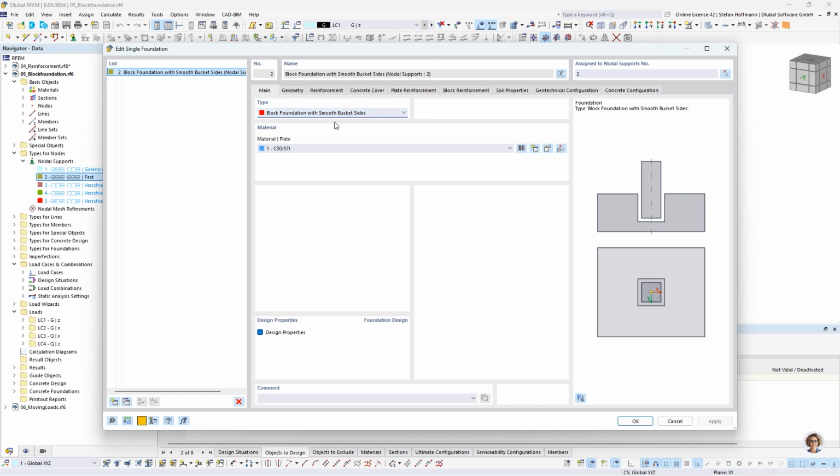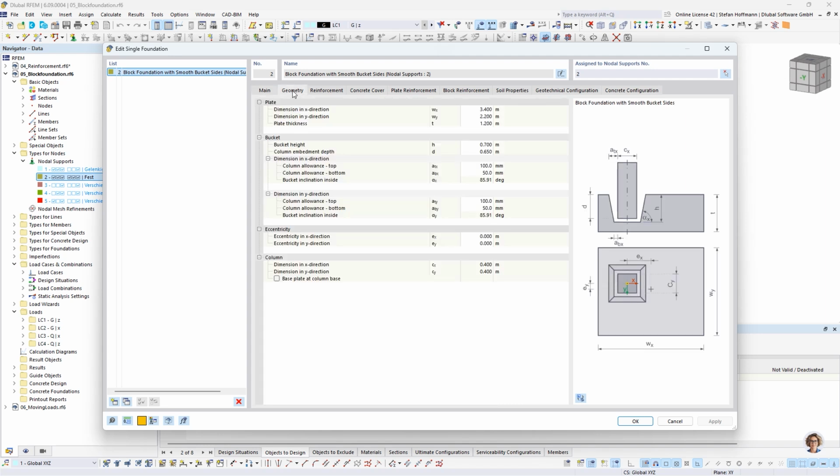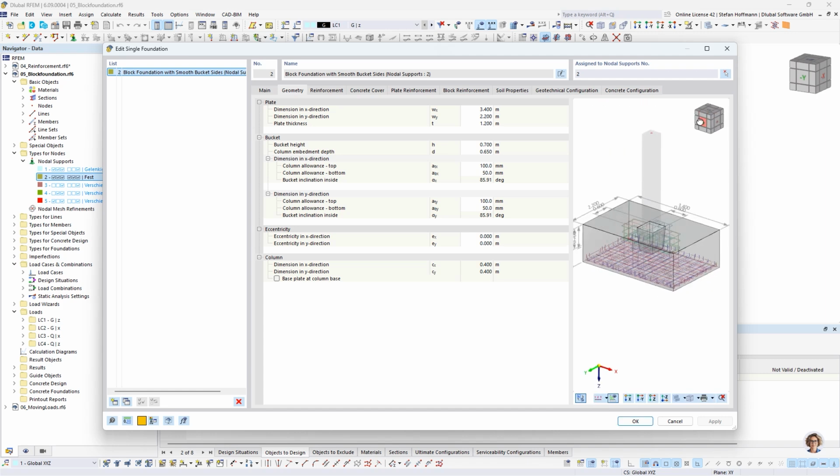So first you need to start with a material of the plate, what you define, and then you can step into the geometry, where you can also define then, of course, geometry by checking the sketch, or you simply switch into the full view, where you can also use the view cube in order to rotate your model to see if it fits for your column and your purpose.